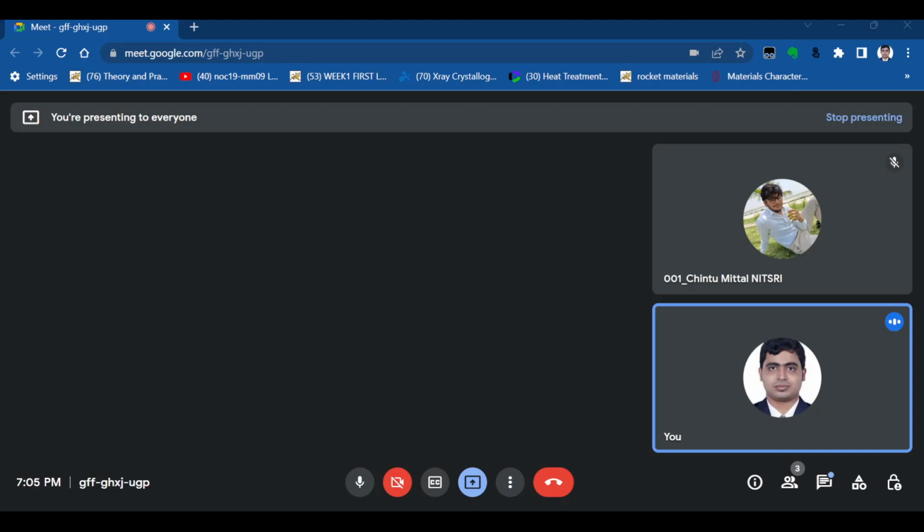So first let us have some idea about what the Tresca yield criteria is. This is if principal stresses are given, and sigma max minus sigma min by 2 is our maximum shear stress. Okay, so this we also can see if we draw a Mohr circle.